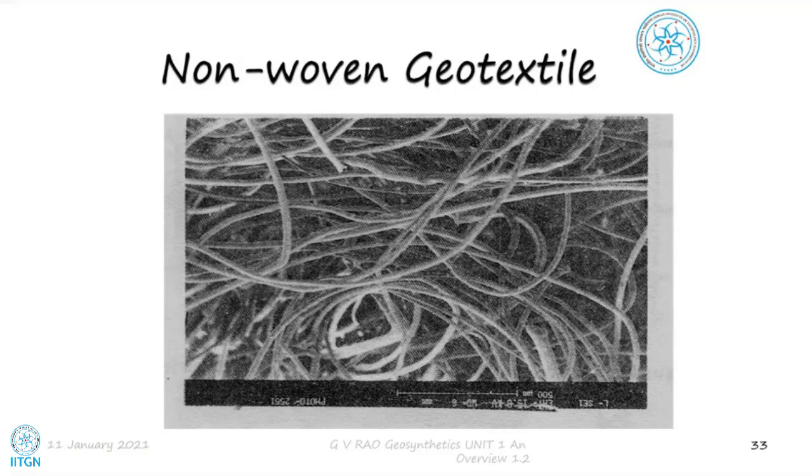Okay, so if you think of an earthen rockfill dam, the thickness of each of the gradations could be 1 meter. And so, for example, the total filter thickness could have been in meters width actually. Here, I got these changes done in less than 1 meter thickness of the geotextile because we are now getting directly the opening size by this now. That means by a reverse method, I have got openings which are different in size and shape. That is wonderful now. So that is the advantage of a blanket kind of geotextile, which is non-woven geotextile.